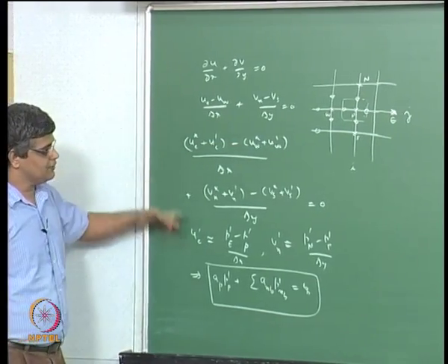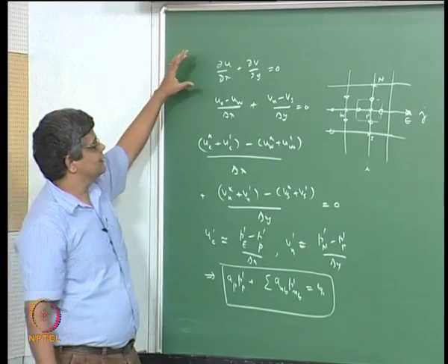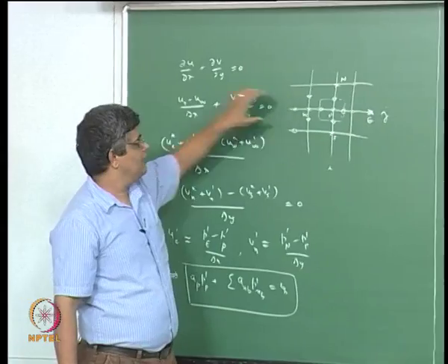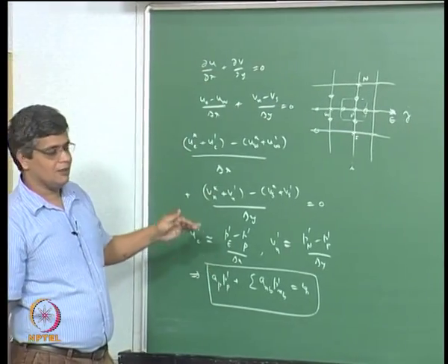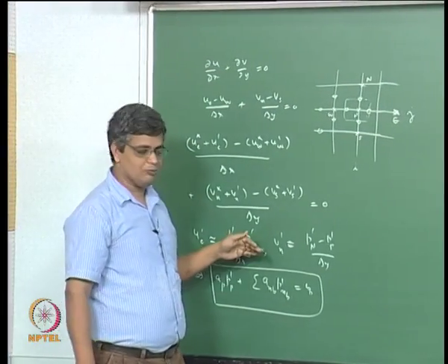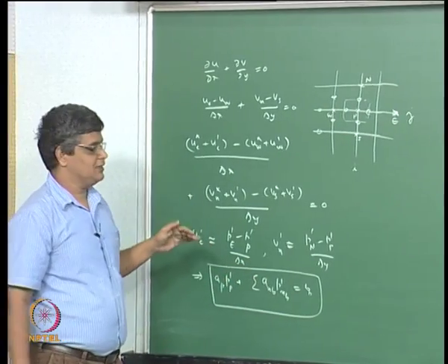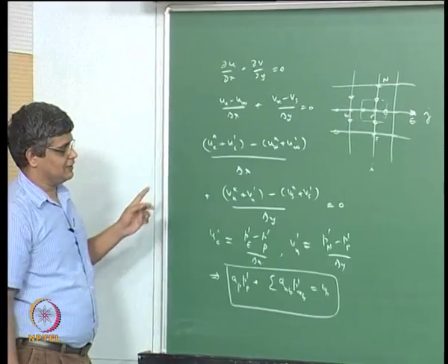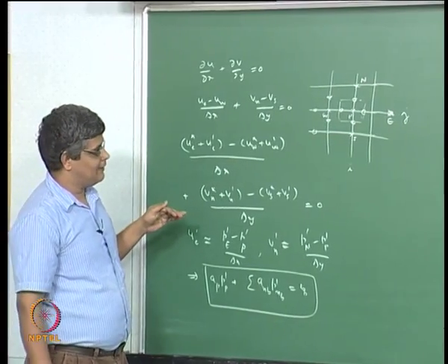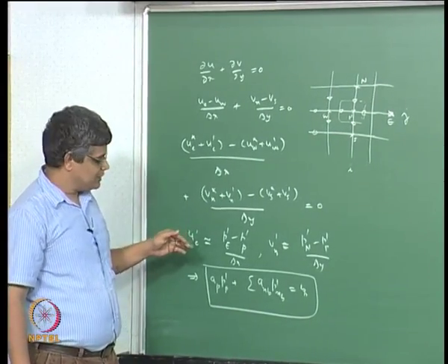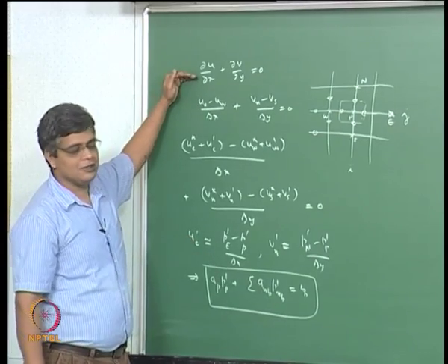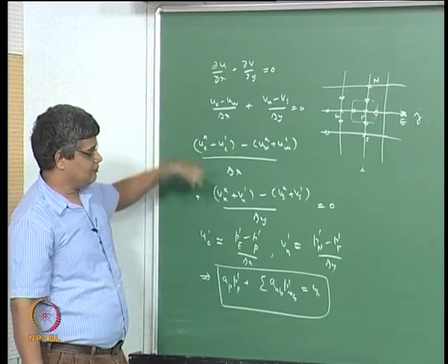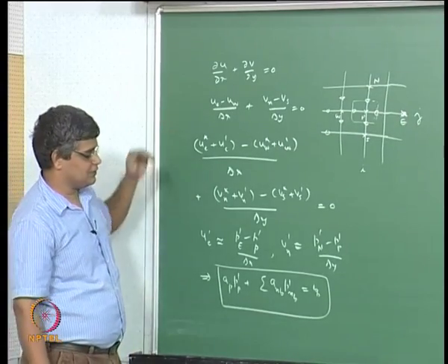So that is a standard way that we discretize the momentum equation on a staggered grid, and thereby enable the determination of pressure, which is not linked to density in the case of incompressible flows. So this creates a means of using the pressure as a continuity enforcing method, a continuity enforcing condition.